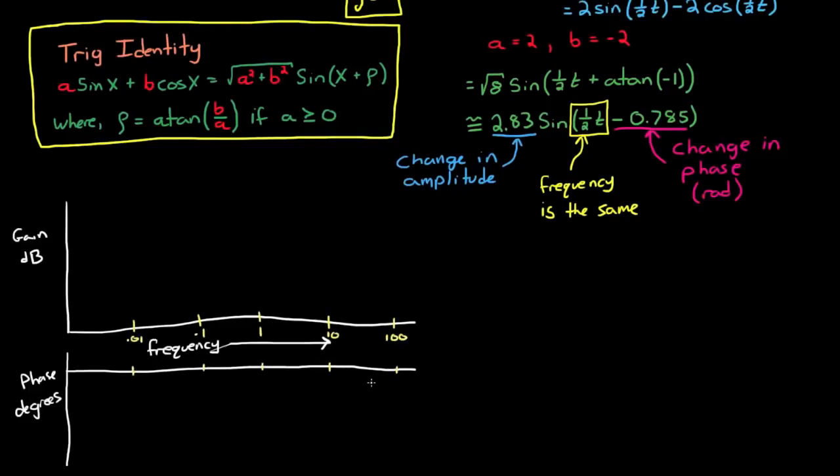But there's a caveat to plotting amplitude gain on a Bode diagram. We don't just plot the magnitude of the gain directly. First, we have to convert it into power, and then we represent the power gain in decibels, which is a logarithmic unit. To convert the amplitude to decibels, you first take the log base 10 of the ratio of amplitudes and then multiply it by 20.